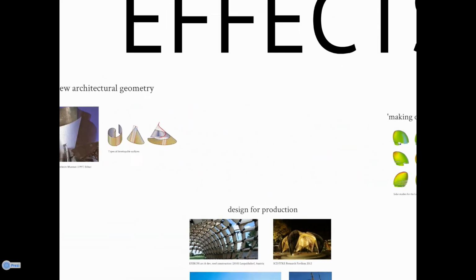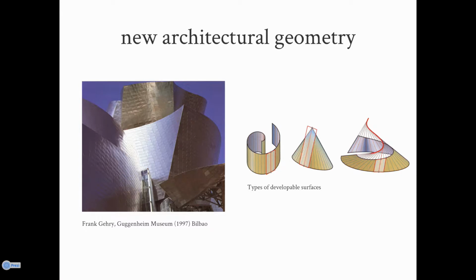Of course, computer-aided design has increased the shape universe that architects can explore, and the software has made it very easy for architects to create very beautifully looking designs, and it's almost the same effort to create a straight line or a spline or a plane or a work surface. However, the geometrical principles behind these shapes are very different and need to be understood. And usually the problems occur when it comes to the construction of these elements. And then it requires a deeper understanding about, for example, curvature, subdivision, offsets, and what are developable surfaces in this specific case, for example.